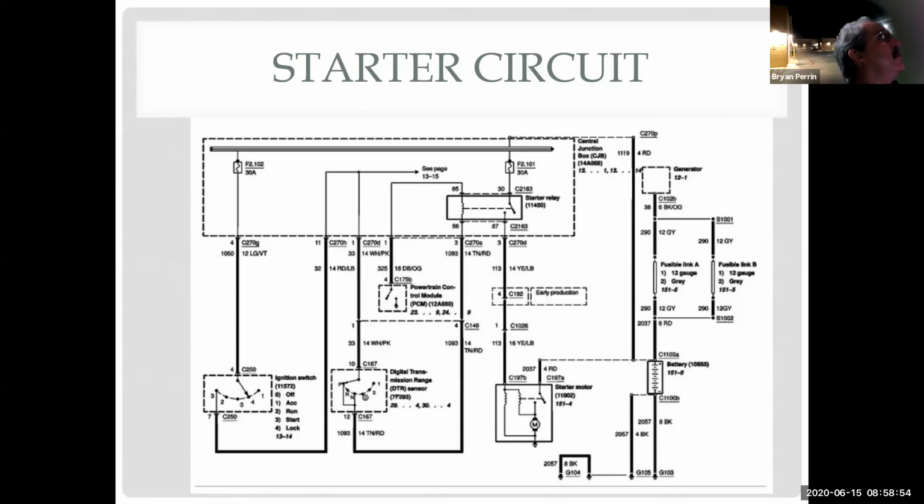Okay. So this switch is open and I see it's controlled here by a coil that pulls it in. This happens to be a solenoid. It's drawn very similar to a relay. So we got to do that to pull this in. If I look here, this goes up and this goes across and feeds power to here and here. So I could come over to here and look, okay, I got power here and it goes to an open switch. That's my second open switch.